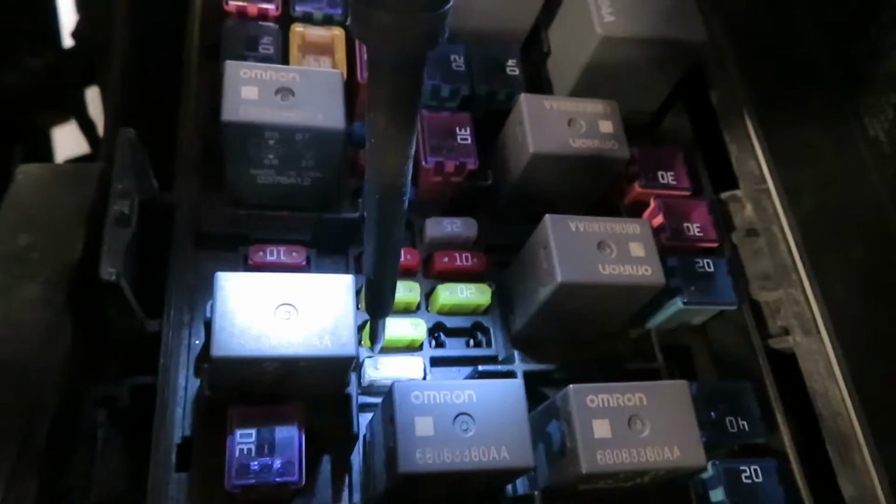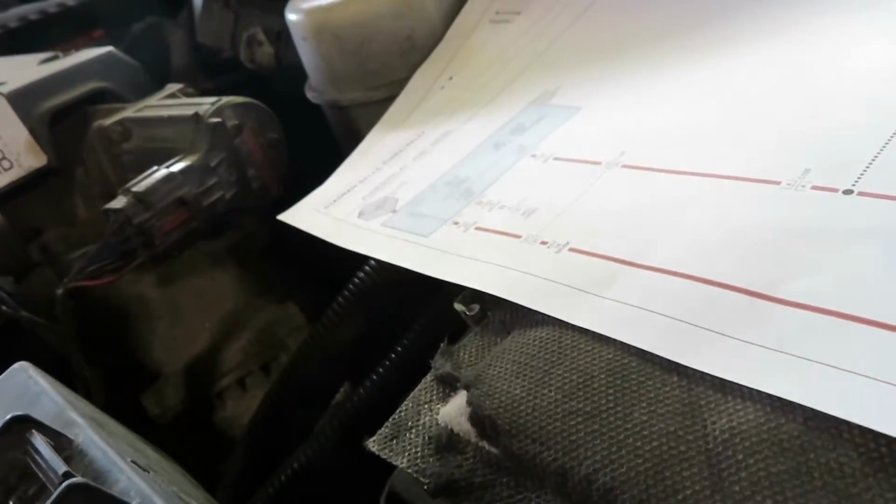On 19, 21 is right beside it. And we have the same deal here. No power going to the fuses. If you come over here to the mass airflow and the EGR bypass valve, you'll find the same deal on the circuits going over here. There will be little to no voltage on it because the circuit's supposed to have battery voltage, but since there's no voltage going to it, you're getting codes for all the separate systems.